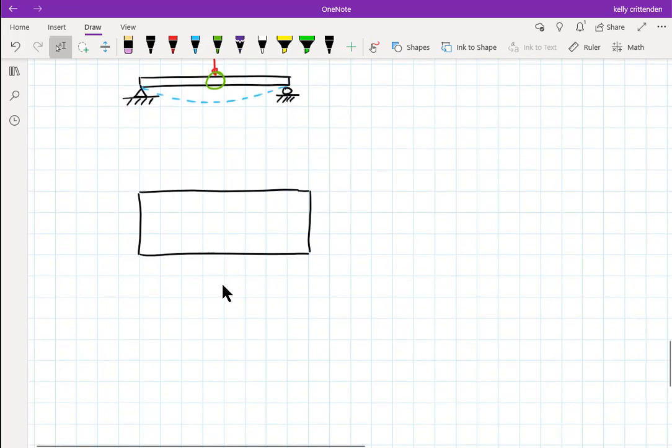And so that means that we kind of chopped it off here and here. Somehow we cut that open so we can see internal stresses and internal forces. And what's going on here, if I pushed hard enough straight down and the beam was a material that just sheared, like cutting it with scissors, then there's some amount of force that's just trying to shear this beam. There's just a shear force.